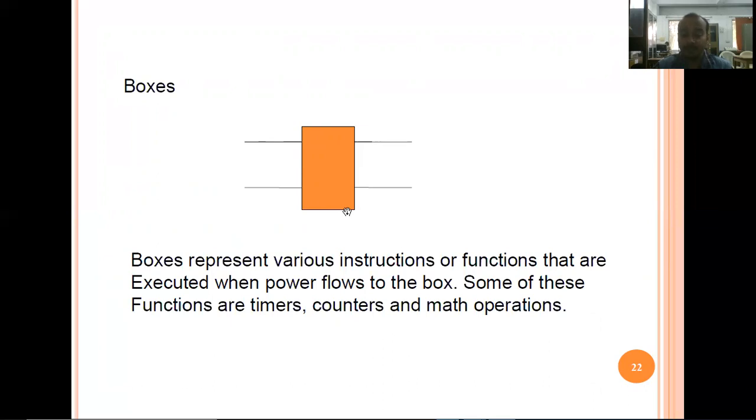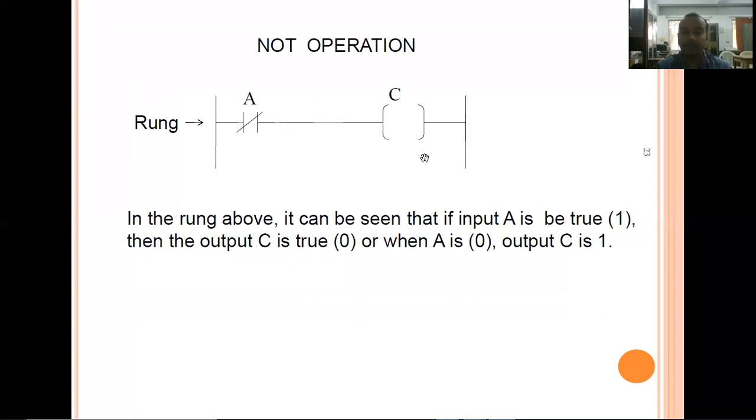In a bottling plant, if you want to count how many bottles pass through a conveyor belt, a counter can be added into the ladder logic. Similarly, if the motor should switch on for a fixed time and after that switch off, the timer can be acted through this box in the ladder logic, and according to this timer the operation will happen.